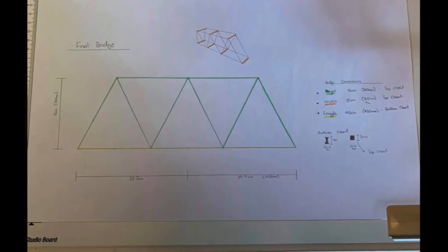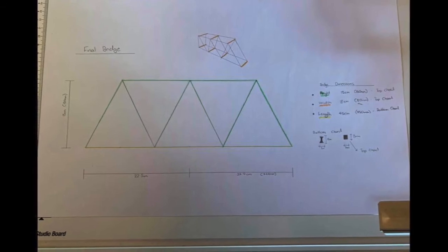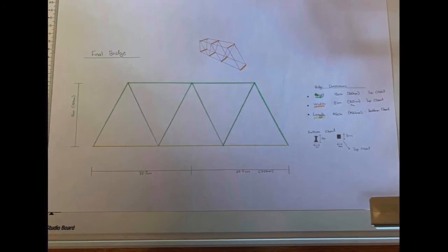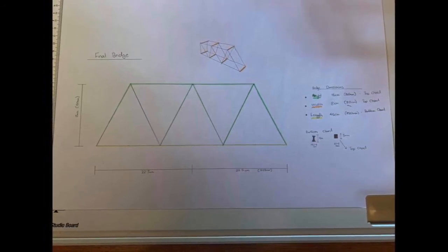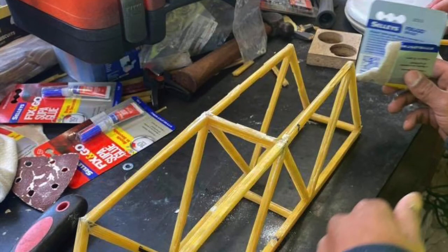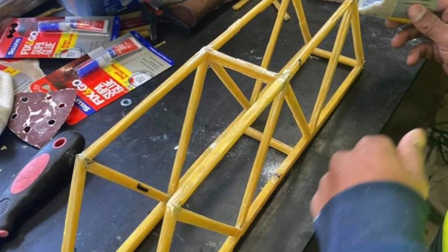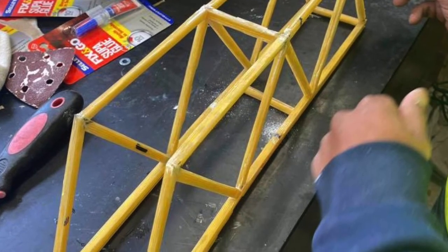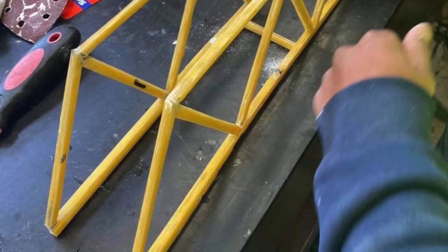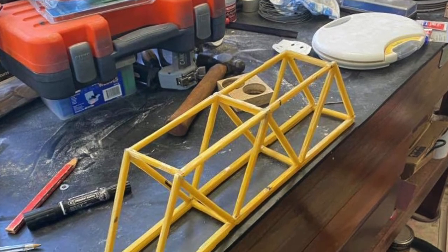Our truss bridge spanned 350 millimeters, had a width of 80 millimeters, and a height of 150 millimeters. This bridge, along with the final bridge we made, was made up of only equilateral triangles. This is because although angles such as 30 degrees and 45 degrees excel in different scenarios, factoring in human error, 60-degree angles perform better as a whole and make for a simpler design, minimizing mistakes. The test bridge weighed 174 grams, significantly under the required weight, and managed to bear 9 kilograms.